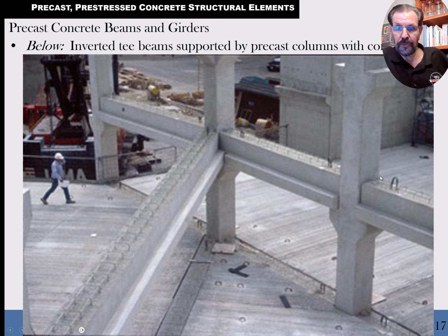They will also sit this beam down on that corbel, but with a little rubber pad, a high-grade neoprene rubber that might be, well, depending on what size, 6 inches by 12 inches wide or something. But the idea is it's kind of like your mouth guard. If you have trouble grinding your teeth at night, you might get a mouth guard that you wear so you're not grinding your enamel off your teeth.